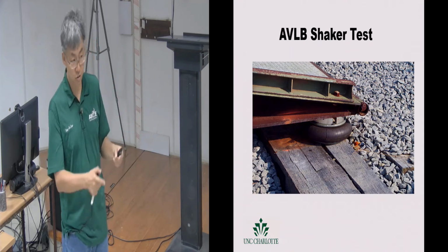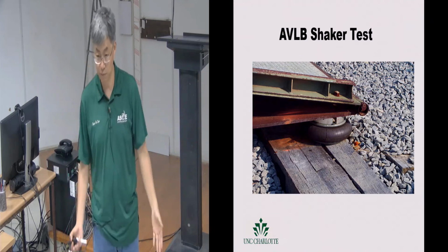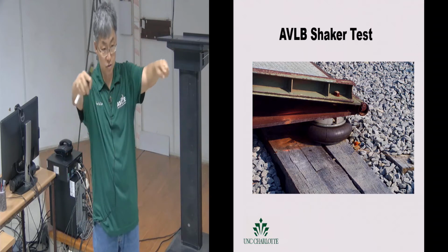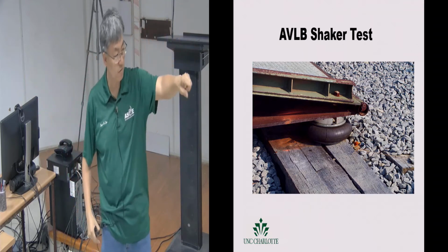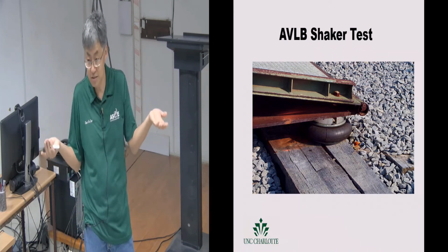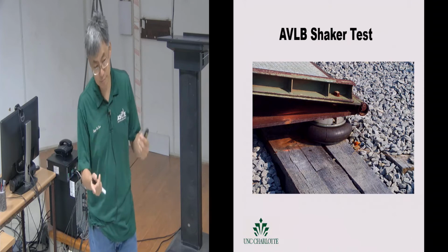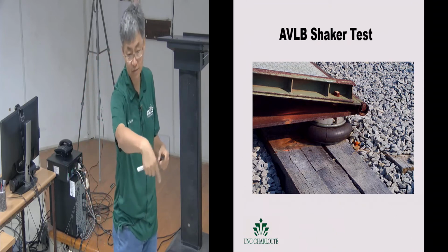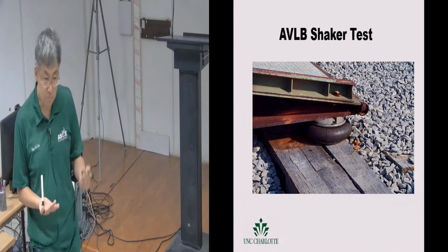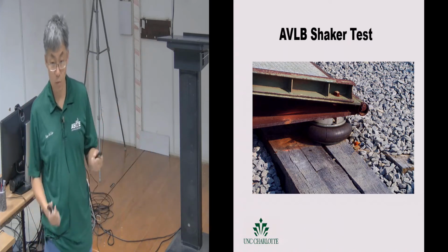So for example, if I were to test this slab on the higher level, and I wanted to make sure that I have fixed boundaries, I can put heavy sandbags around, so the boundaries have strong rigidity when you do the testing, provided your goal is to find damage in the middle and not the connection. Those are tricks that you just learn when you are doing work in the field.